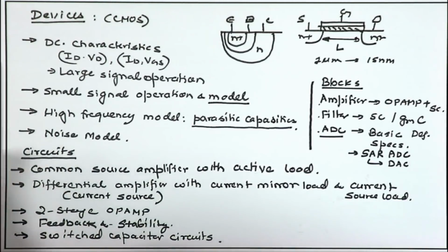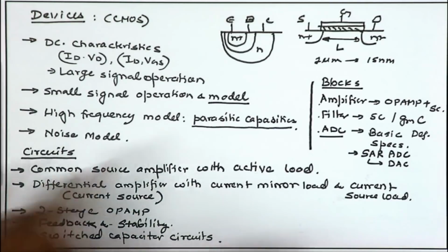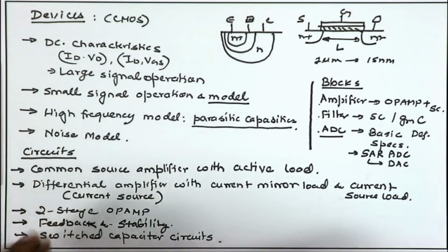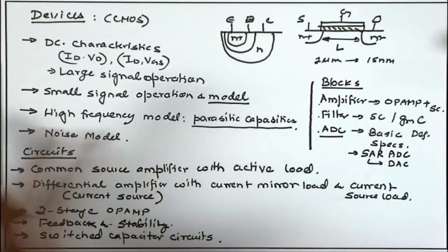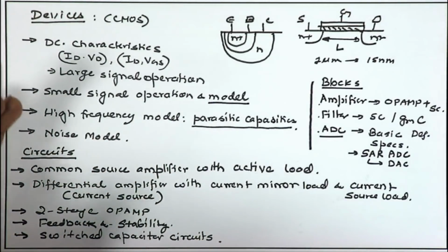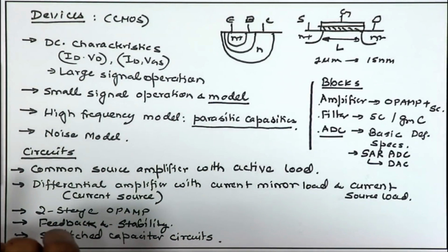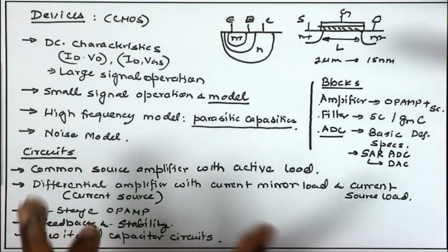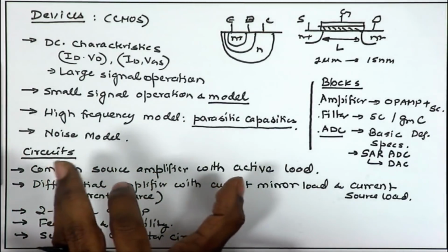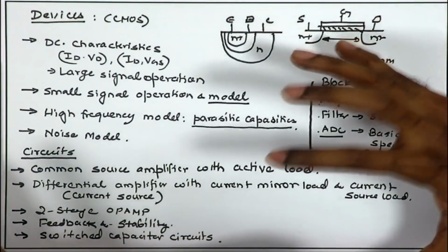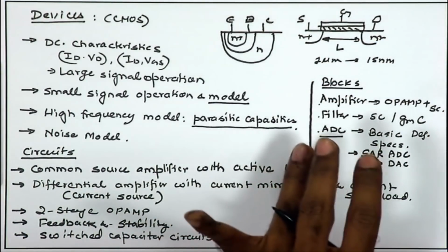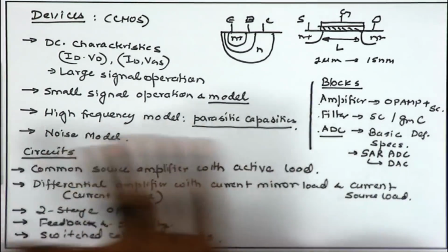You can have some interaction between the DSP part and the analog part. The digital part may need to give some instruction to the analog part to tune it, to calibrate it, program it or configure it according to the desired input signal. So, there is a tight interaction between the analog part and the digital part. In today's age, it is not very practical to confine ourselves only to the analog or only to the digital part, because these two things are getting so tightly linked.